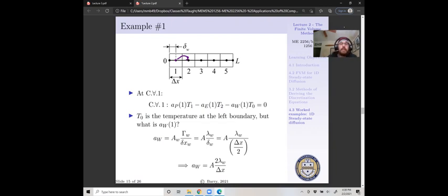But all we had to do is recognize that we could take this value at our boundary, T naught, and it'd have a leading coefficient, A west. Now, A west was equal to the interfacial area, which would be this area, times the diffusivity at that boundary per delta XW. Now, delta XW is just 1/2 of delta X, right down here. So AW was then multiplied by a factor of 2 in comparison to everywhere else.